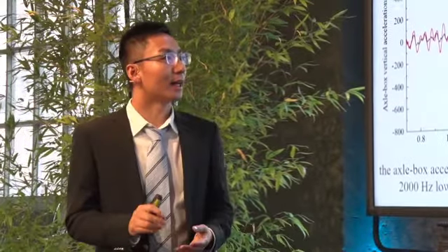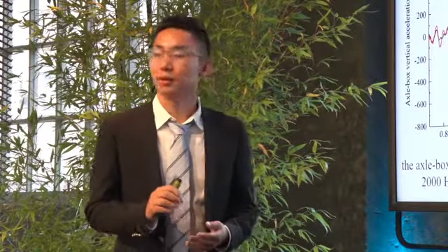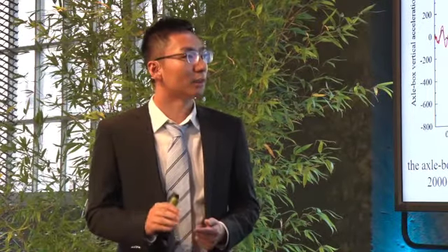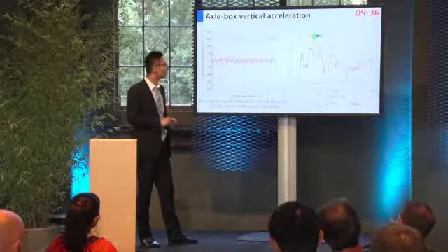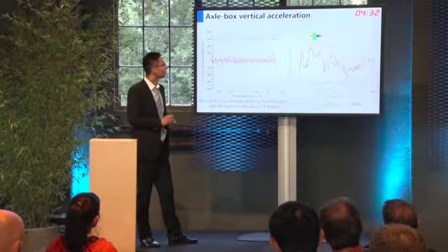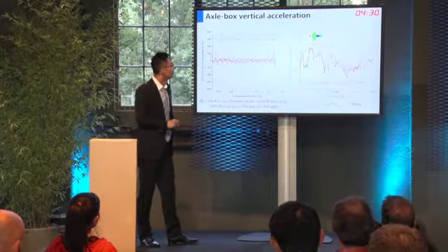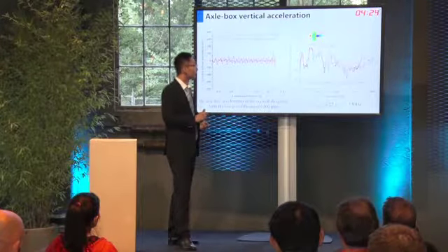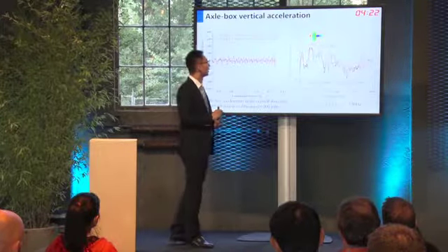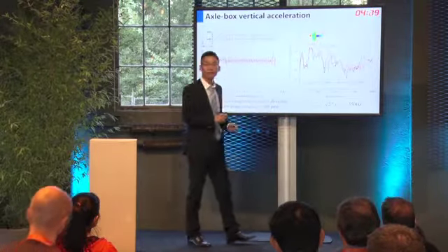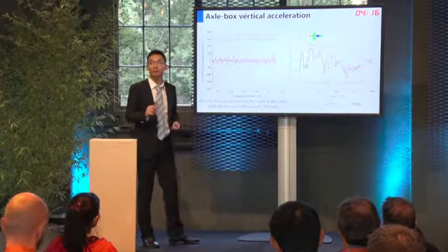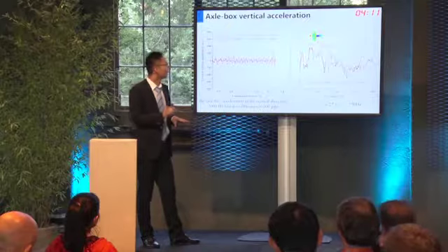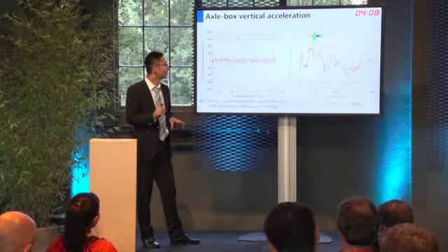For the 80 millimeter wavelength, the resilient wheel can also reduce the acceleration of the axle box effectively above 550 Hertz. It's worth noting that the excitation frequency of the calculation with 80 millimeter wavelength is about 278 Hertz, which is lower than 550 Hertz. So the acceleration is slightly increased.